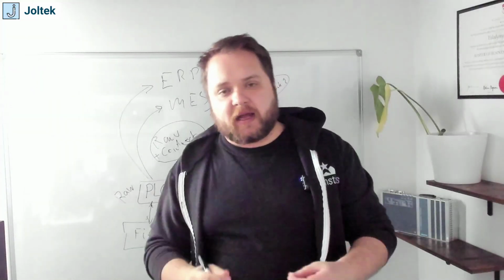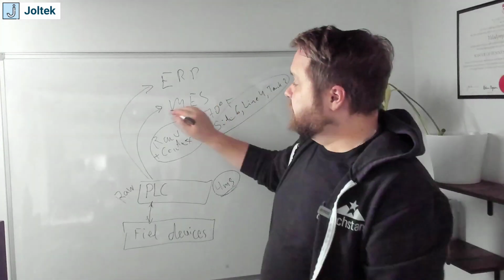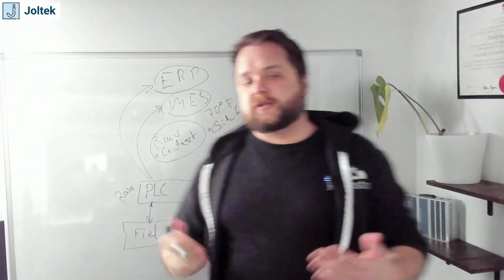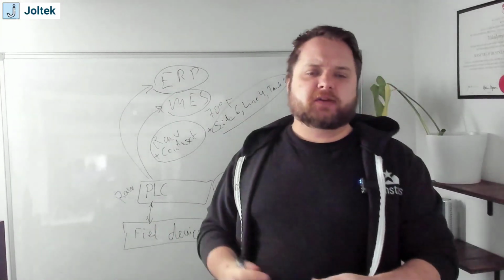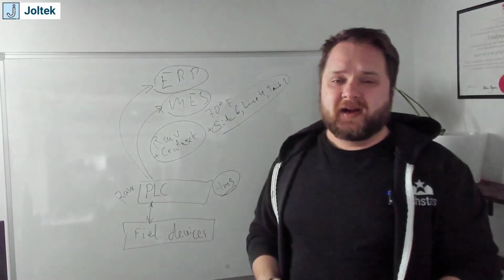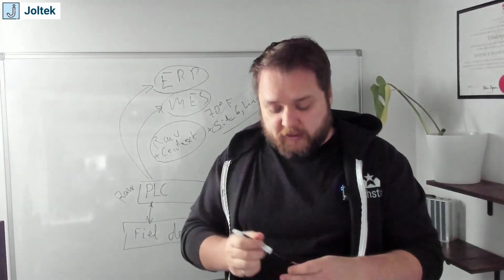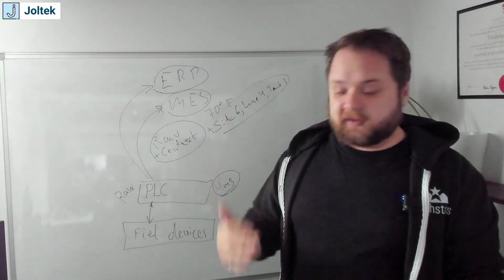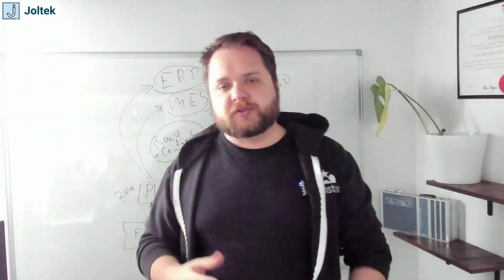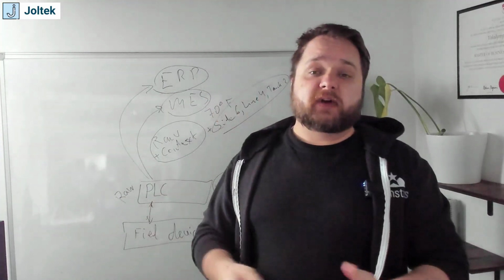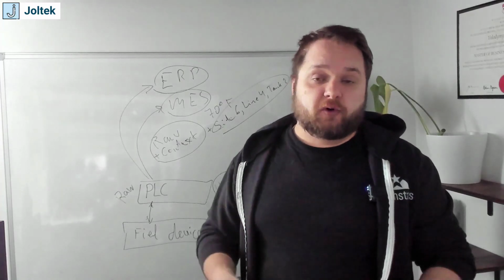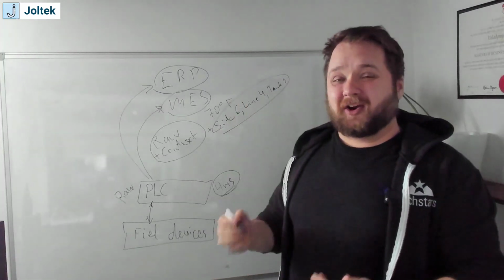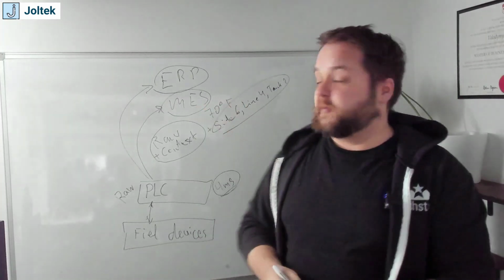As I said, it can be added in multiple ways. It can be added at the MES layer, it can be added at the ERP layer, it can also be added on what's called the edge. Like I said, PLCs are not really good at manipulating strings, therefore it's very rare that you would spend the time necessary to go in and tag every single value that you need to pass along at the PLC level. So normally what you would see is an edge device, right? An edge device is nothing more than a computer or an IPC, industrial personal computer, which ultimately means that it can add that context before funneling that information upwards.